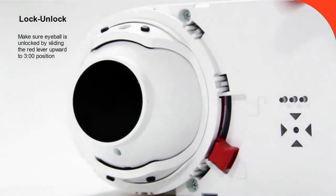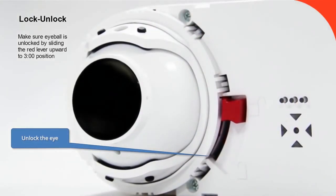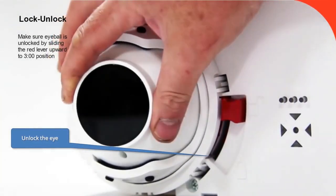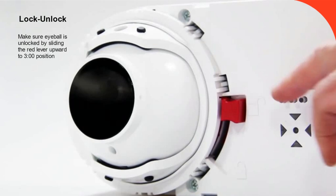Installation, lock and unlock. Once the detector is mounted and powered, you can start the alignment. To start the alignment, make sure the red lever is in the unlocked position. This allows for simple operation while working at height with no risk of dropping a tool, causing delays in installation.